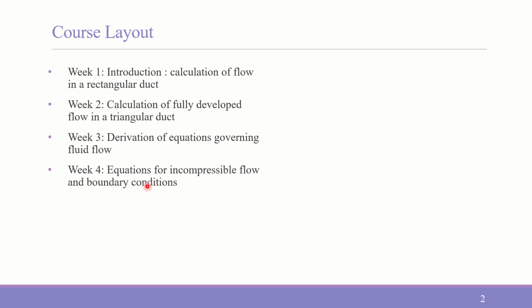It is nothing but incompressible flow. We have the Navier-Stokes equations, and along with that we apply boundary conditions at the boundary points. For example, if we are talking about fluid flow in a circular pipe, we give the inlet velocity, that is one boundary condition. We give a no slip wall, that is one boundary condition, and at the other end we give pressure outlet, that is one boundary condition. So basically we are specifying the values at the boundaries in terms of inlet, wall or outlet. All along these regions we specify the values, that is known as boundary conditions.